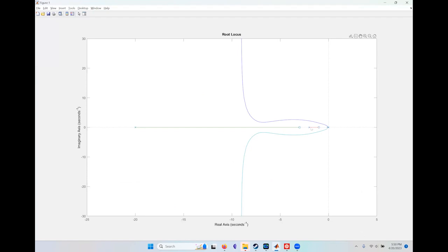You can see the two poles here. One pole gets attracted to this zero, the other pole gets attracted to the other zero. The two poles that are closer to the origin do this behavior, but things are getting better. The two poles are moving away from the j omega axis. So that's fine. This tells me I can pick some gain.